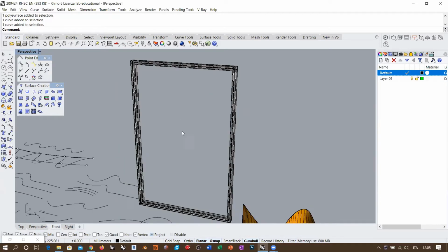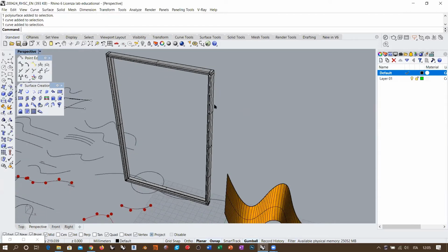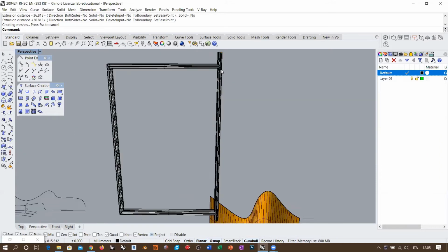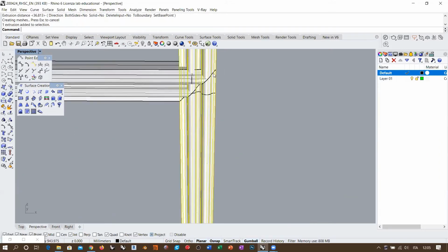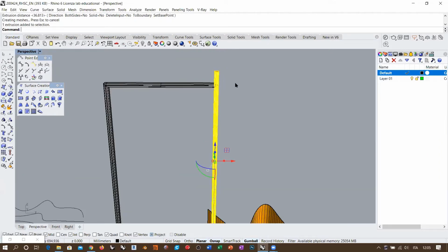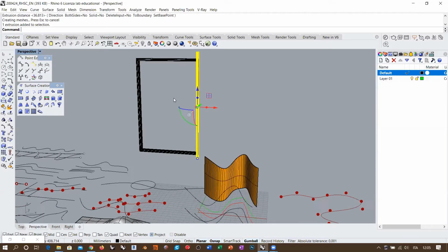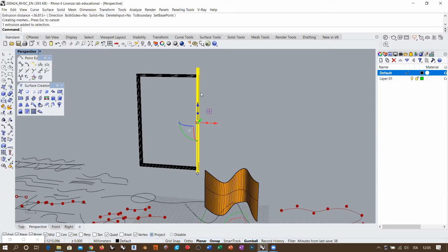So you see that the sweep is not producing the best result possible. Eventually, you can take this cross section here, create some kind of straight extrusion like this, which is higher than the edge itself, and then eventually start to mirror this 45-degree, create the upper side, mirror it, and have the lower side, and mirror this on the other hand, and have the left side, which are basically one single extrusion.